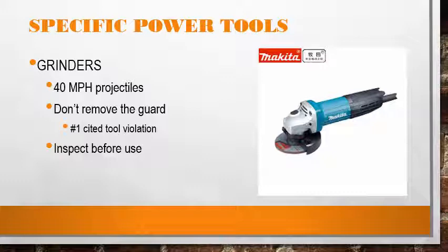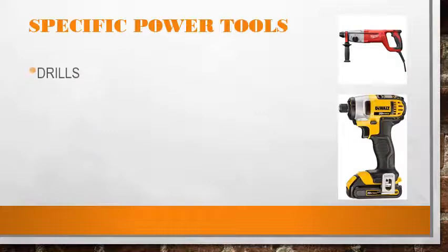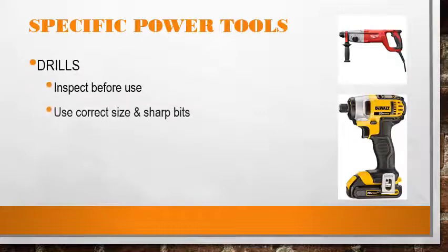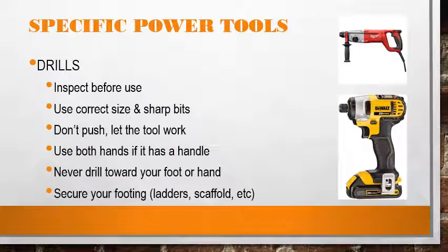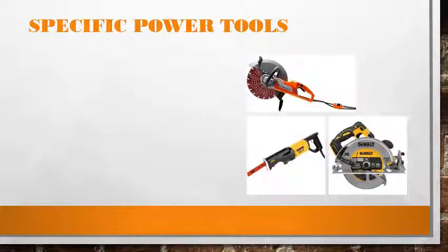If you're using a drill, inspect before use. Use correct size and sharp bits. Don't push the drill. Let the tool do the work. Use both hands if it has a handle. Never drill toward your hand or foot, and make sure you have secure footing underneath you if you're on a ladder or scaffold.